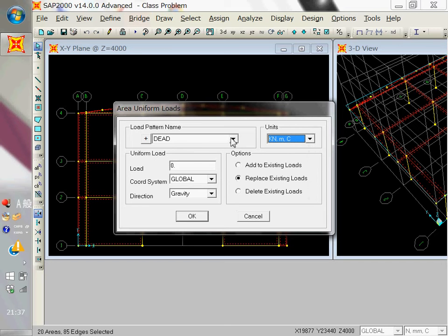And there is no need to apply that load, because I told you we have kept this as a self weight, and the SAP will calculate this self weight by its own function. So we will assign surface finish load. We already assigned surface finish load that day, but if you want to reassign, you can again give the value over here, okay, and you can check this box, replace existing load. If you check this box and add a value here, it will replace the existing load. You understand?